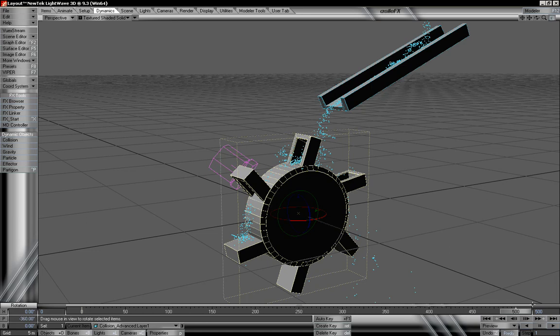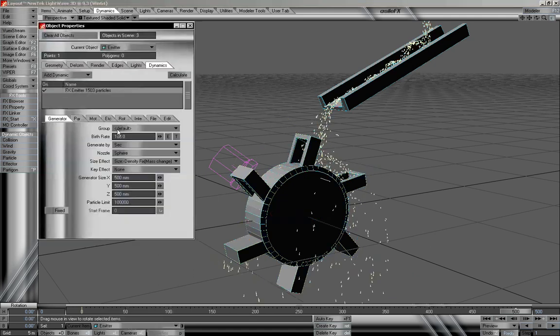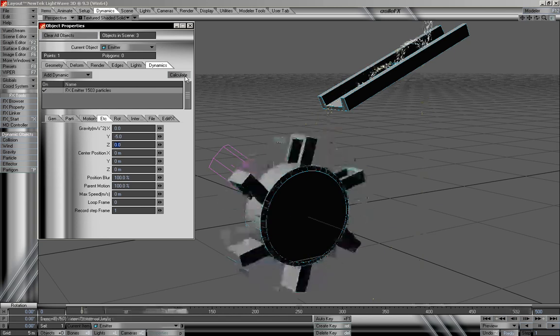So let's go ahead to our last frame, and I'm going to take our pitch and decrease this from negative 360 to negative 600. Actually an increase, but since we're going negative, technically a decrease. And then I want to select our emitter object, and under the gravity, change that to negative 5. And I'm going to recalculate this now, and then we can take a look at something a little bit quicker, and that will follow along in the animation a little bit further.